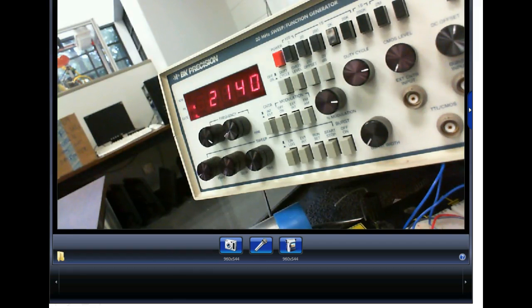Because in a linear power supply, your filters have to run the load for the time between peaks, right? You understand? If I can make those peaks closer together by increasing the frequency, that means the size of your filters can go way down. And that's one of the advantages of the switching power supply.